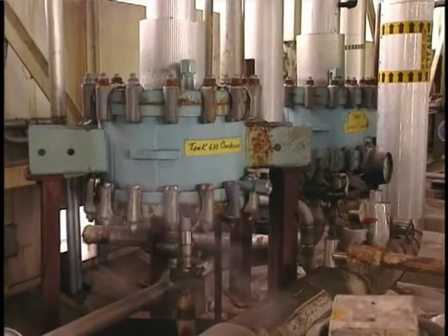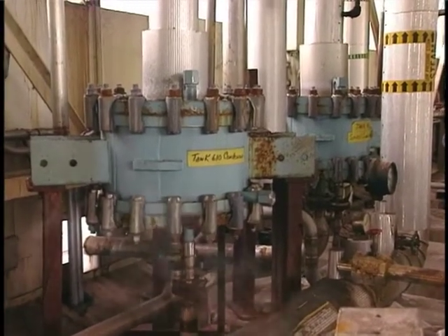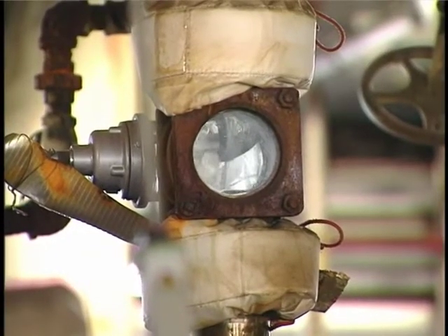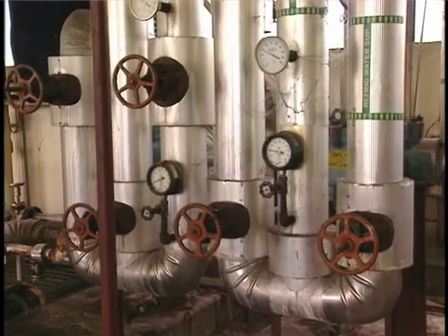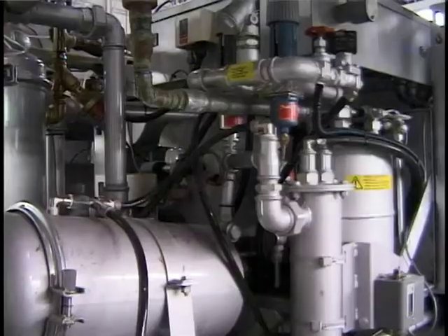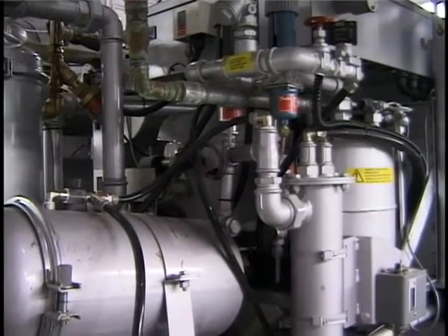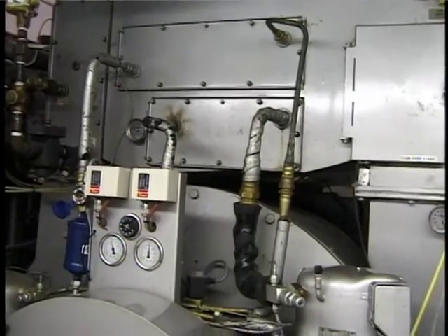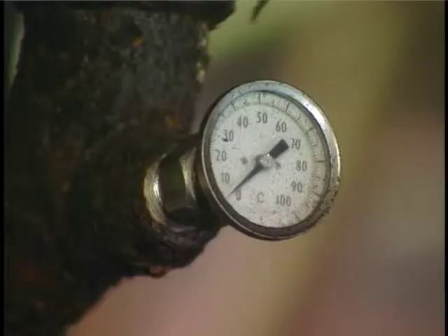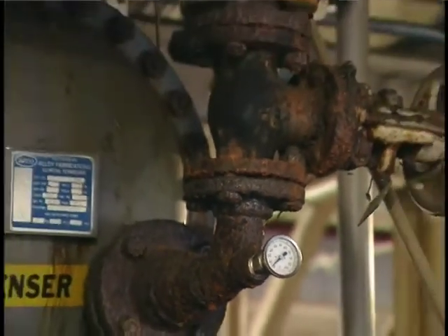In condensation processes, gaseous contaminants are removed from a gas stream by causing them to change to a liquid. In general, this can be accomplished by increasing the pressure or reducing the temperature, or by a combination of both. However, because of the cost of operating and maintaining compression equipment, most condensers for air pollution control use temperature reduction. The ultimate efficiency of a condenser depends on the operating temperature.